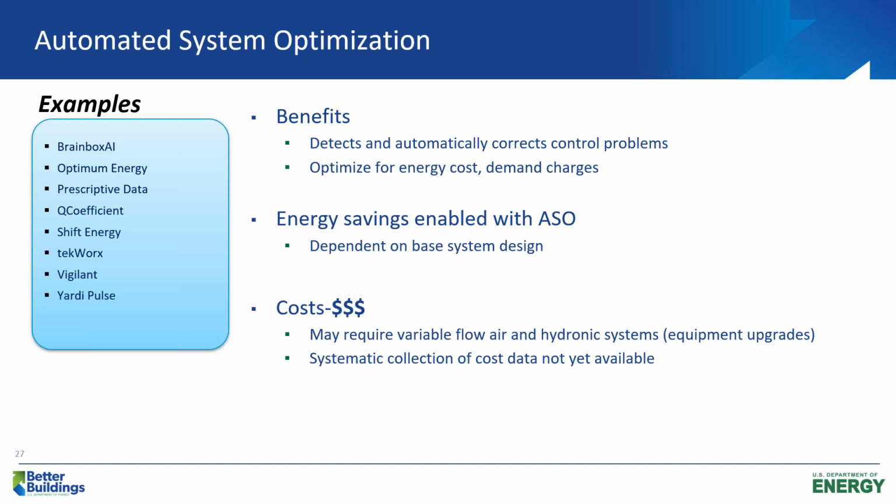And the real benefit here is that you're optimizing in real time. It's generally focused on systems that are larger, that are either variable flow already, or you're willing to do a retrofit to variable flow, air and water side. So it really requires that level of tuning and optimization ability.